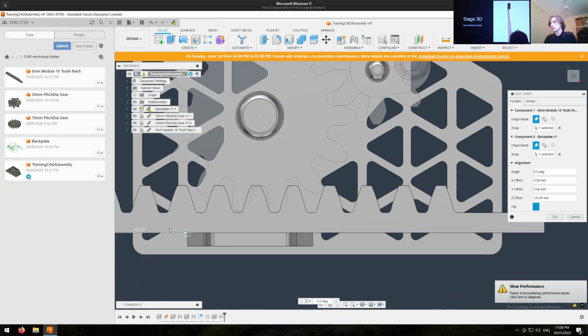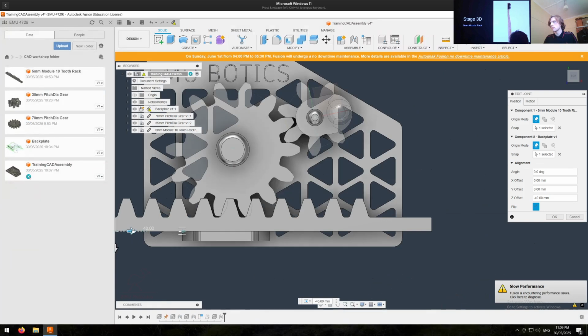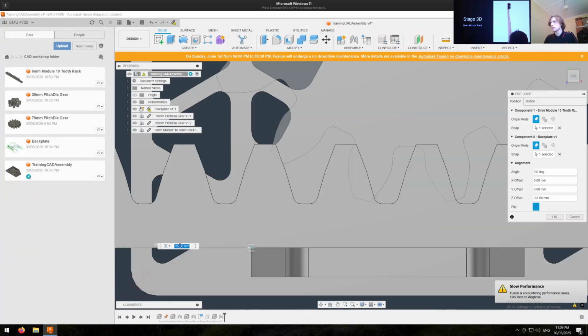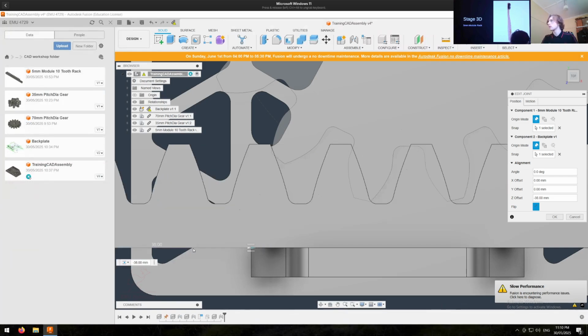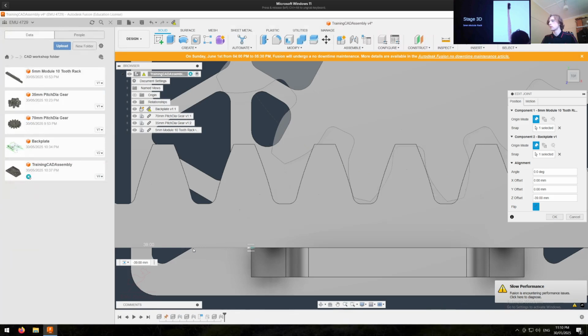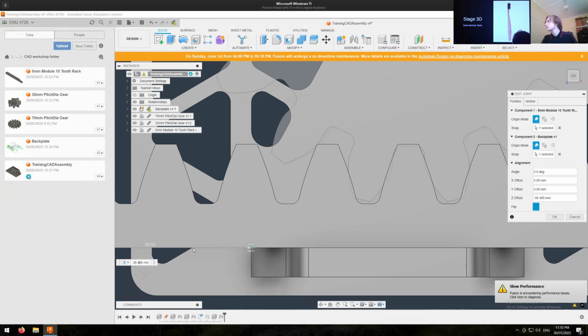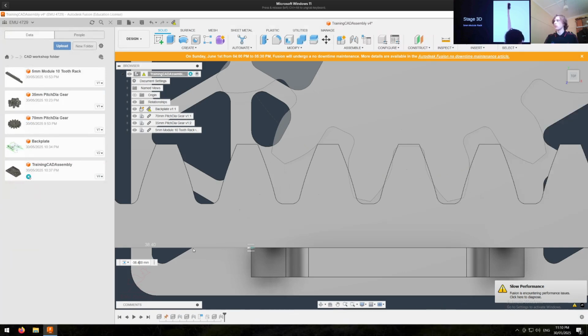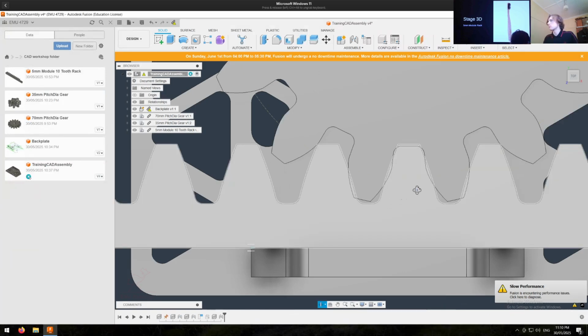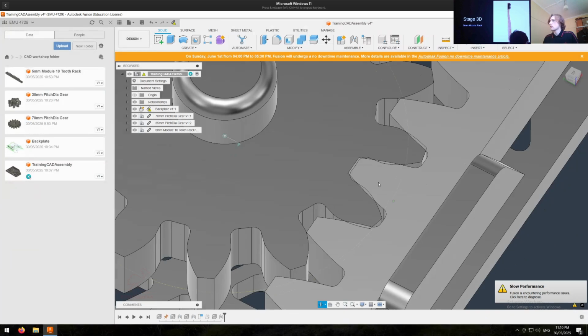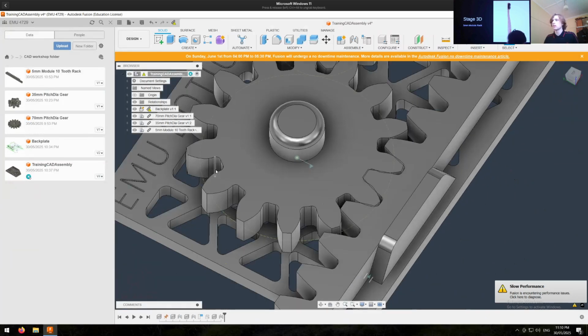So where is it? Oh, it's like this one. I'm going to make it 15, 35, 36, 37, 38. Oh, so it's kind of like 38. That's going to be 38.5. 4. There we go. It's right in the middle. But we have a problem. They're kind of binding. You can see that. So before we fix up our motion link, we do need to fix that binding.